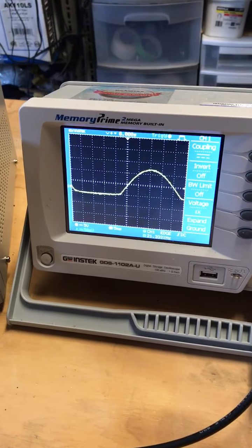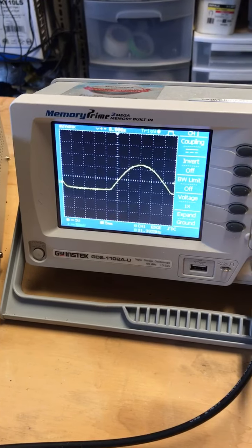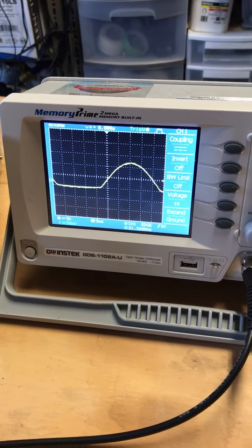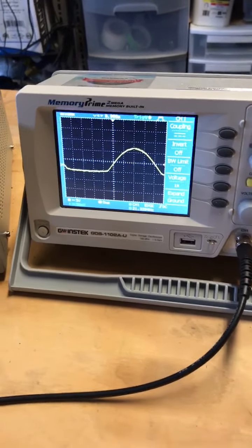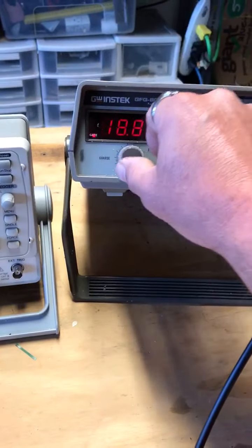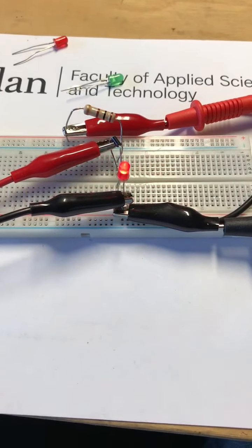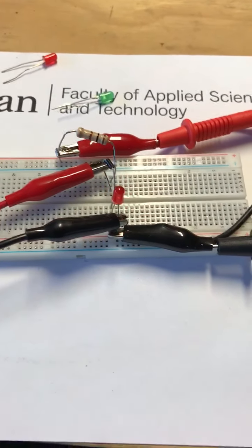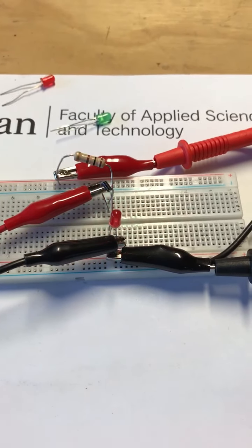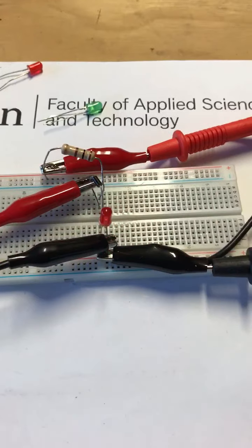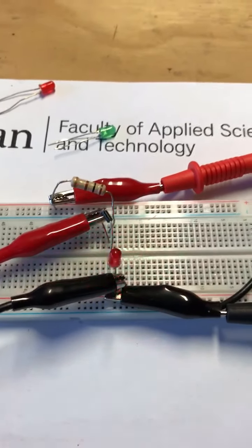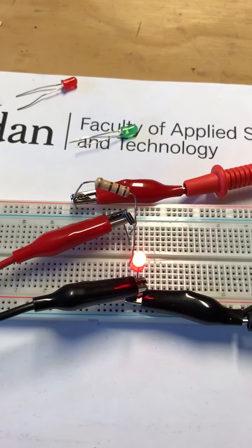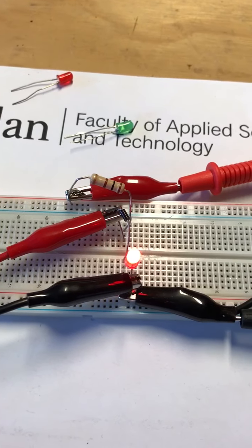We can see the amount of off time equals the amount of on time, but there's a bigger time period in between the two, so you get the flashing. So I'm going to decrease the frequency a little more even. I'll look at it now. So as you decrease the frequency, you get more time period in between the off and the on cycle, so it causes this flashing. I'll bring it back up. Once you get up to around 40, it smooths out.